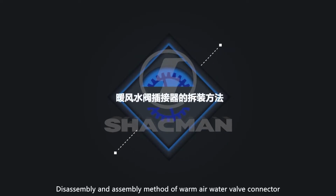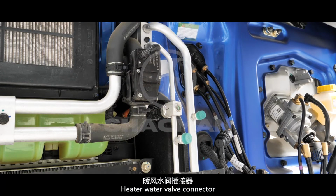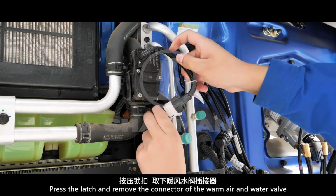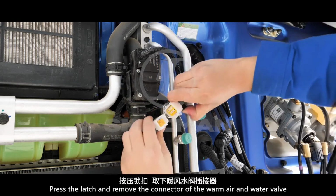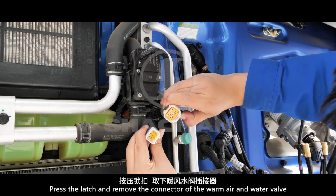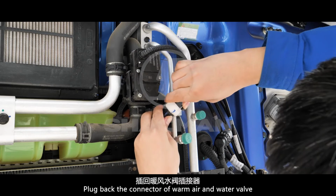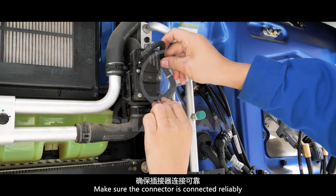Disassembly and assembly method of warm air water valve connector. Heater water valve connector. Press the latch and remove the connector of the warm air and water valve. Plug back the connector of the warm air and water valve. Make sure the connector is connected reliably.